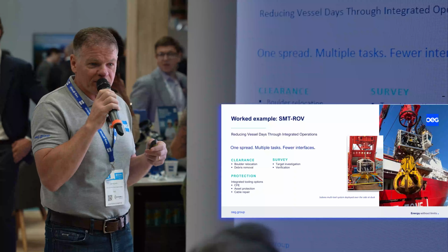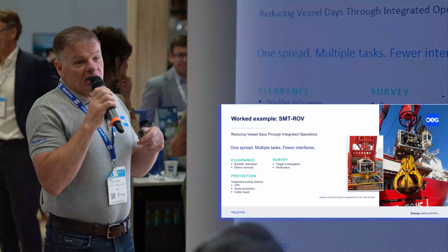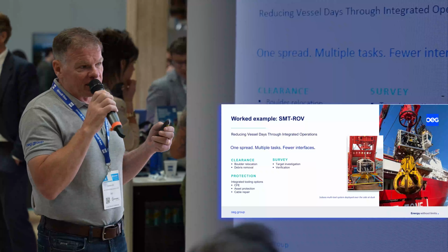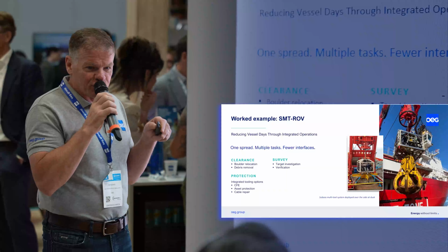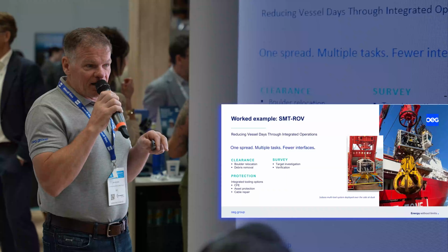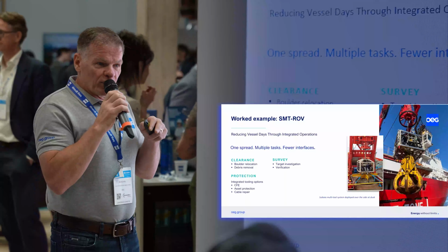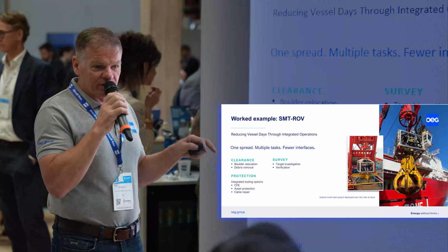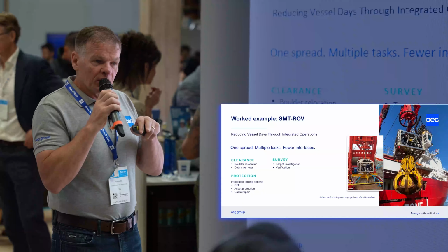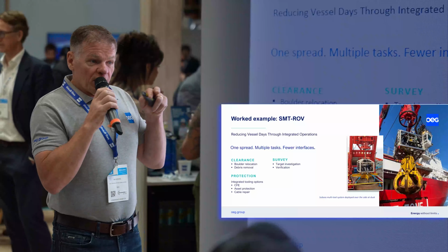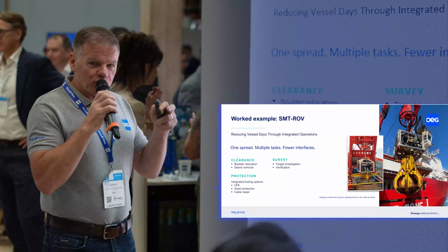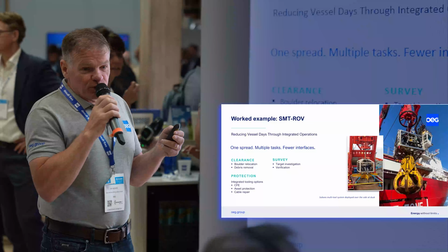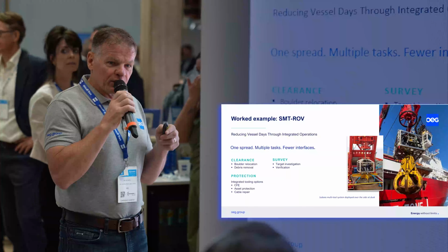So when we're looking at the system, we can plug in multibeams. It has BlueView systems, low light cameras. So every target that we actually identify with this system, it takes a picture of it, logs that as part of the data. A whole report is then generated where we've picked it up, moved it to, and placed it down. So then the client has a total record, usually within 24 hours, as we're moving on the cable paths or the jack-up places. Everything's moved, data logged, recorded, videoed, photographed.